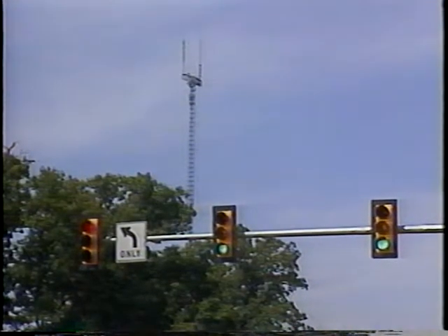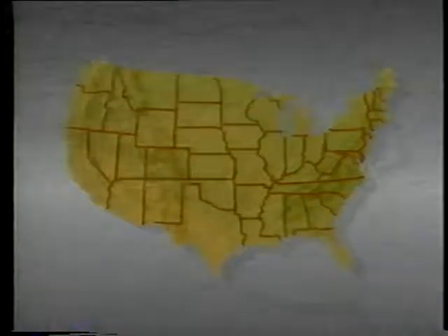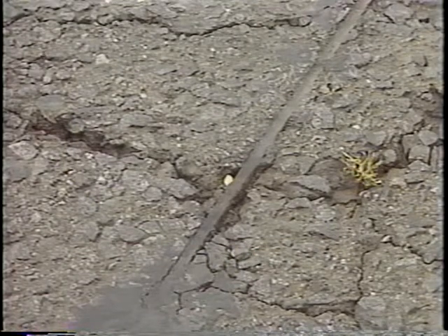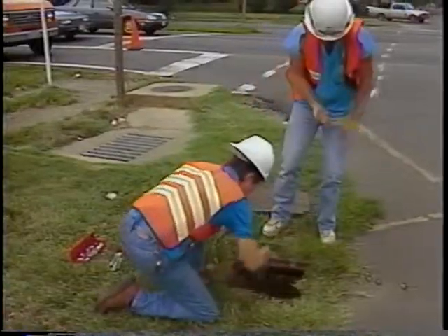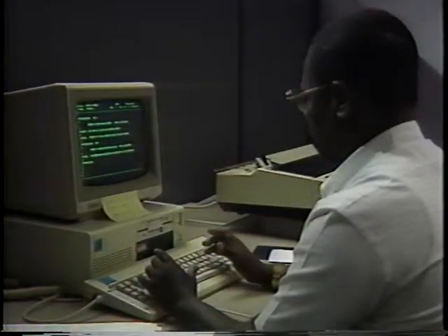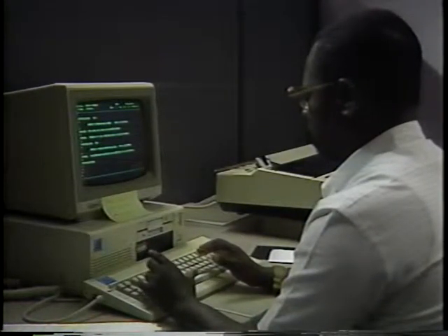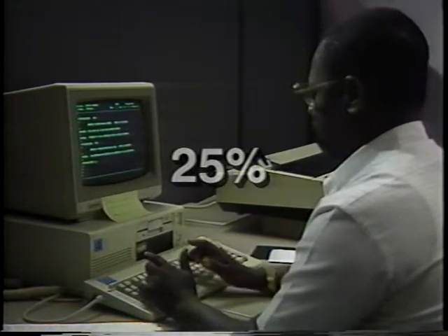Long-term effective operation is the goal. The large number of loop detector failures nationwide has created a deep concern within the traffic engineering community. A number of studies have traced many loop detector failures to a problem with the in-road loop wire, or to the splice between the lead-in wire and cable. These failures are usually due to bad pavement conditions or sloppy installation techniques. Several state agency surveys have noted that at any given time, up to 25% of their installed loop detectors are not operating properly.